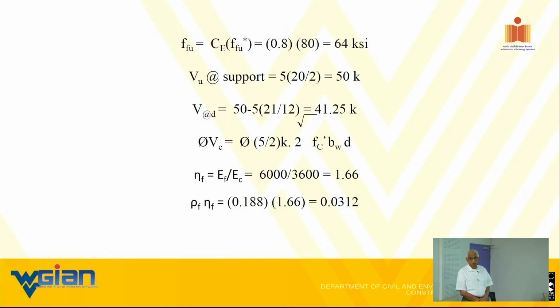And that support, 20-foot span, is, I don't know how much you all do here in terms of shear critical section. Do you all use it at the support, or do you use the critical section at a distance D from the support? Yeah, I want to repeat this. Typically, the critical shear section is at a distance D, the effective depth, from the support. Only, wait a minute, that's a partially correct, partially incorrect statement.